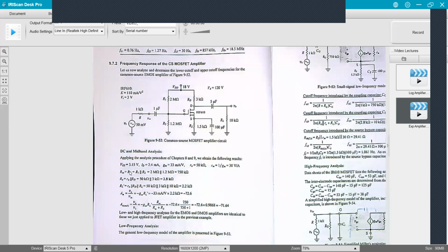If you have other sensors, you have an amplifier for each one of those also. So every one of those will be drawing current. And if they're running off of a battery, the less what's called static current that you draw, the longer your battery lasts, so you don't have to replace it as often. Even if you're running it off of something like batteries that are charged up by solar cells.